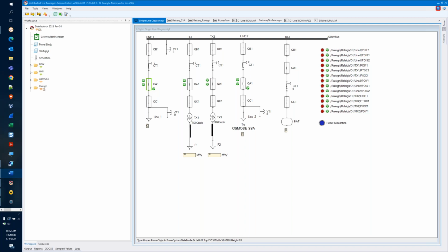So let's start with the first thing I mentioned, the substation section. As mentioned, a well-formed substation section can contain all of the information needed to recreate your single line diagram, which is what we've been able to do here. When DTM, our flagship simulation tool, imports the SCD that we configured earlier over in Helix, you're given the option to generate the corresponding one line automatically, which is what you've seen here. There's not a need to redraw it or transfer it in some other way between the two tools. It's all encoded within that SCD.